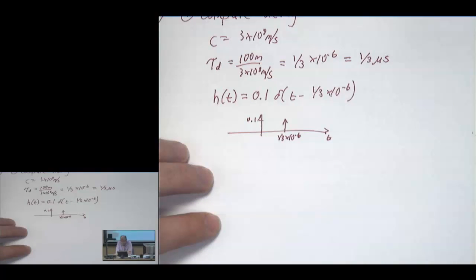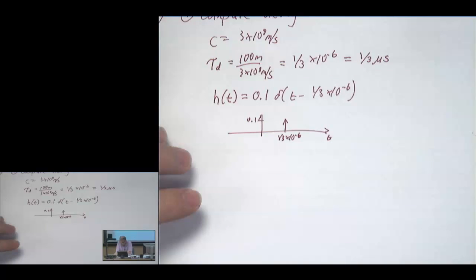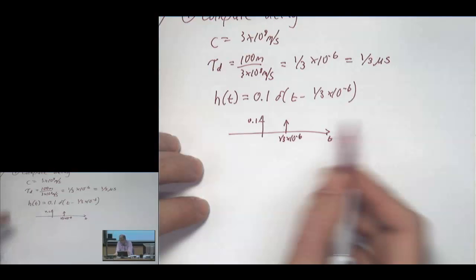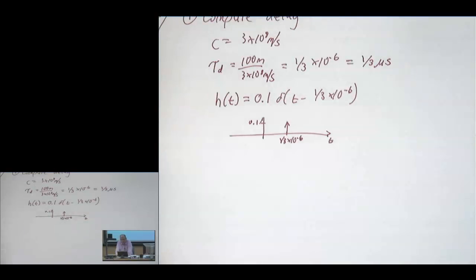And we're going to see that this yields a kind of non-trivial impulse response from what seems like a very trivial example. This is the place where so many people get hung up because they say, well, this is delayed, so obviously I just sample this and I'm good to go. So why can't I sample h of t directly and create the h of n, the discrete time version?